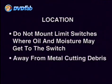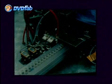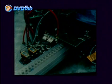Debris from metal cutting could also cause interference as it builds up between the detecting part and the lever of the limit switch. In these applications, you should look for mounting positions where the amount of cutting oil or coolant liquids dripping on the machine are minimal and be sure that you use watertight or oil-tight limit switches.